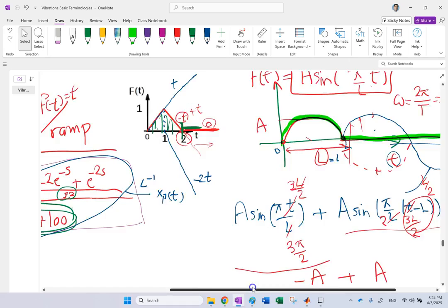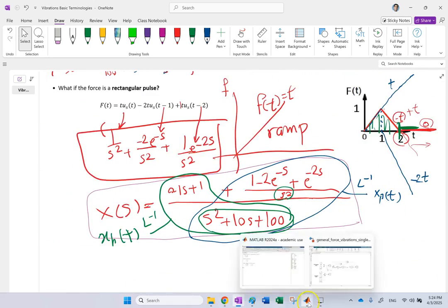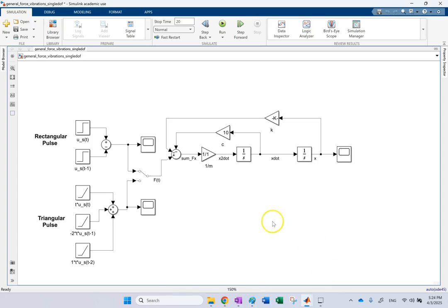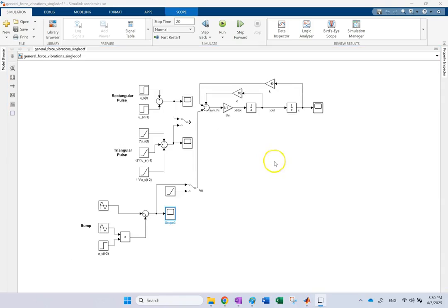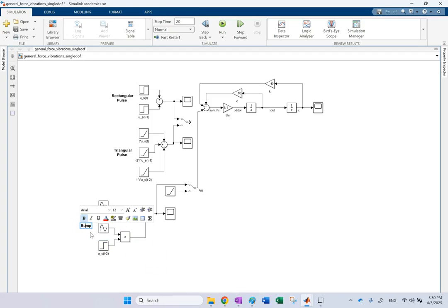And you can simulate a bump as well. So here I can simply go back and I can add a bump if you want, in addition to all of this, and I can simulate that as well. So here I decided to add a bump for you. So here is that sine wave. This is the sine wave multiplied by the step function to limit it to only have non-zero values after so much. The L that I used here is 2.